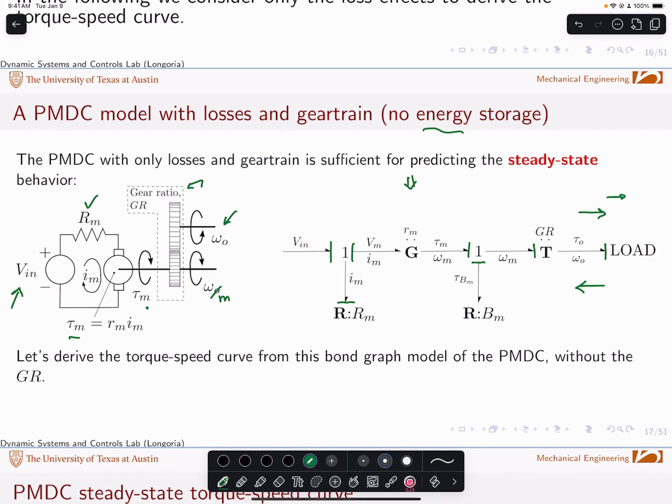So what this is saying physically is that input voltage minus back EMF gives me current. That's what the resistance does. It's basically specifying how much current is flowing through that motor armature at steady state. All the dynamic effects have gone away because you're now running at steady state. It's just losses that are basically describing how this motor performs.